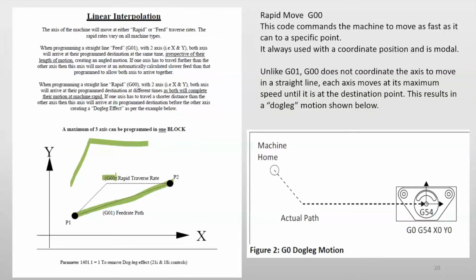I would recommend going back to the video that Diana and I showed you about the CNC machine. You can see one does the cutting. For instance, if it wants to go from here to here, it goes up and does it fast. Those kinds of fast movements are the ones we have as G00.